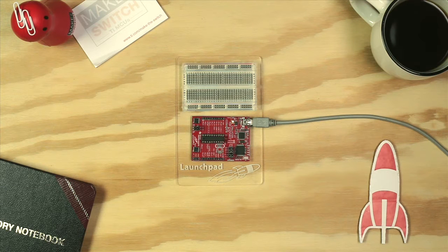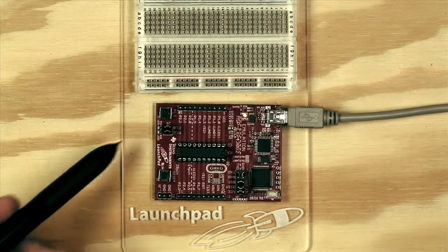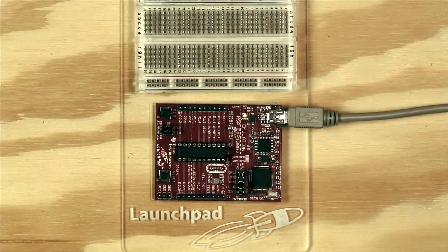You can send bytes to the LaunchPad from any software that can access the computer serial port. For this example, you can either use an external LED or one of the onboard LEDs of the LaunchPad. If you wish to use an external LED, you can rig up a simple circuit using a resistor and LED connected to the LaunchPad as shown in previous tutorials. For most common LEDs, you can usually do without the resistor, as current output of the digital I/O pins is limited. For this example, we can simply use the onboard LED that comes with the LaunchPad.